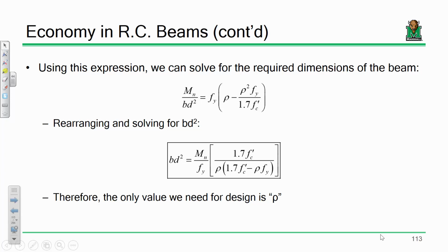So we can sort of determine how much of this we need based on our structure, right? It's a beam that's 22 foot long. It's got 1 kip per foot in dead load and 3 kips per foot in live load. So I can do the analysis and get a factored moment, and that can help me determine how much required Mn I need. So that's actually pretty doable as well.